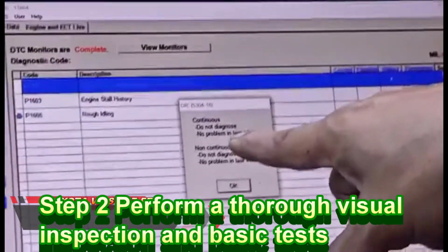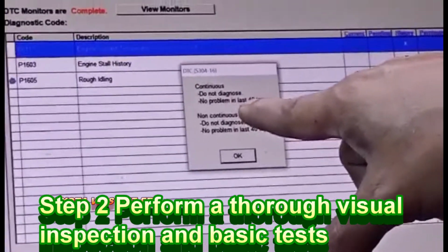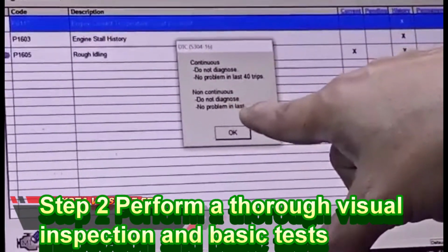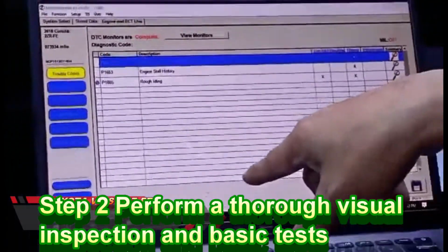Check oil level and condition. Another area for visual inspection is oil level and condition. Oil level: oil should be to the proper level. Oil condition: using a match or lighter, try to light the oil on the dipstick. If the oil flames up, gasoline is present.